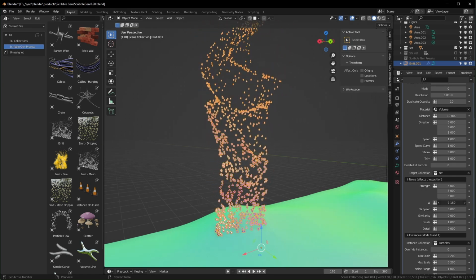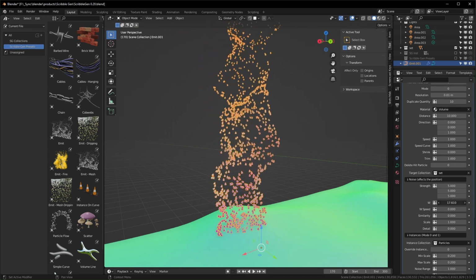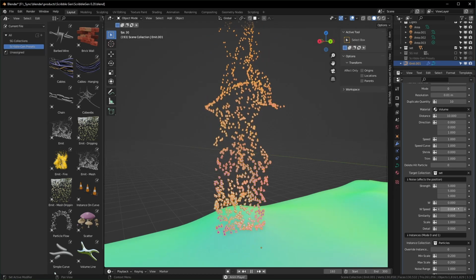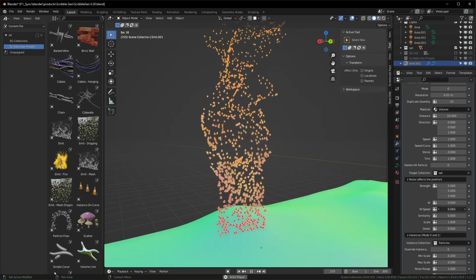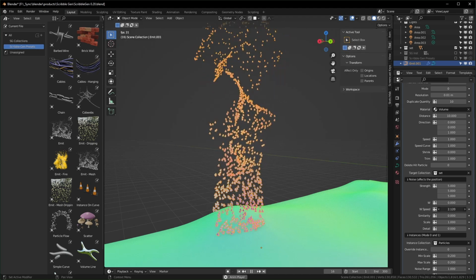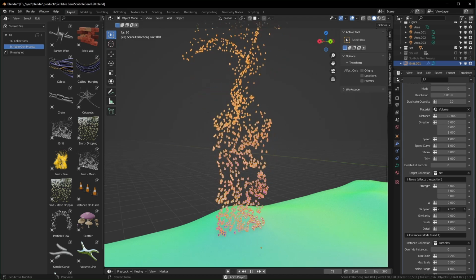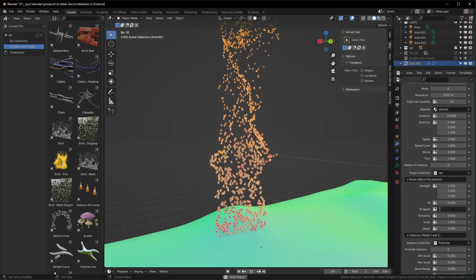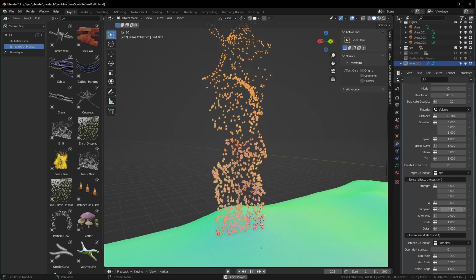W is going to do normal, typical noise texture stuff. This is like a seed. We also have W speed. If you want the W to change over time, then you can do that. It's a little more noticeable when you turn it up high, but I think just setting it to something smaller like 0.2 is a pretty good effect.